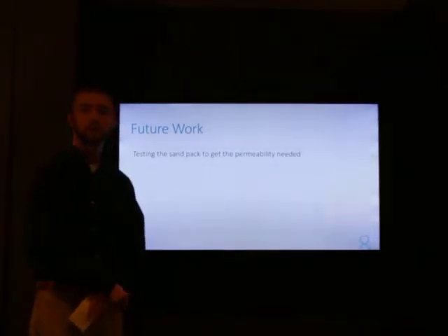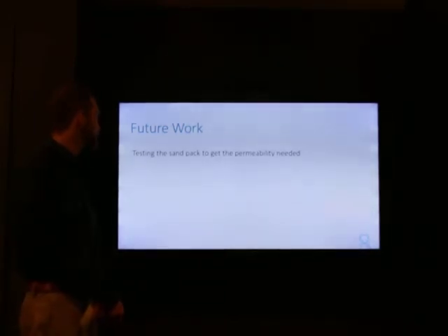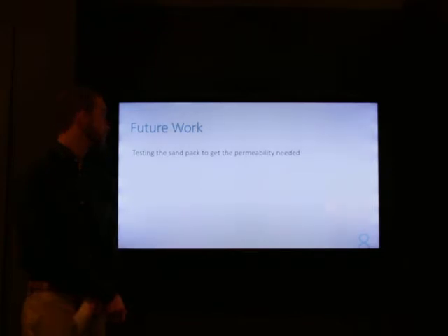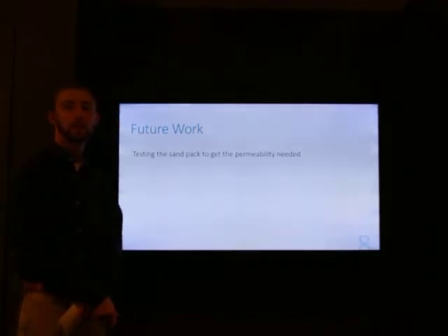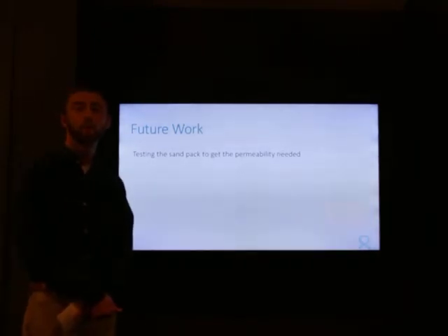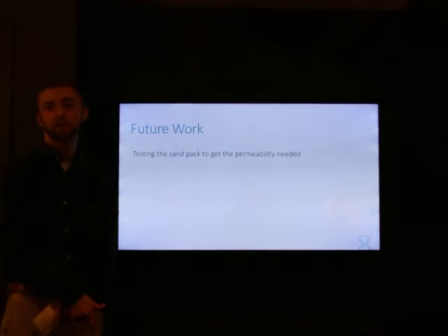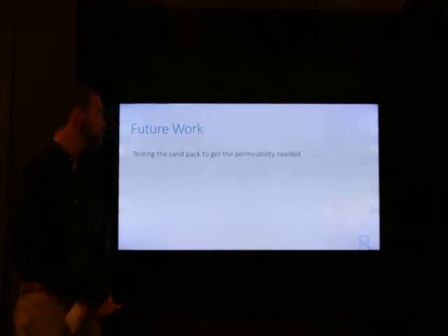So this is the future work that will need to be completed in order to finish this project. The first thing we're going to need to do is to test the sand pack in order to get the permeability that we need. We would ideally like the permeability of our sand pack to be 1 to 3 Darcy in order for our experiment to be completed in a reasonable amount of time.